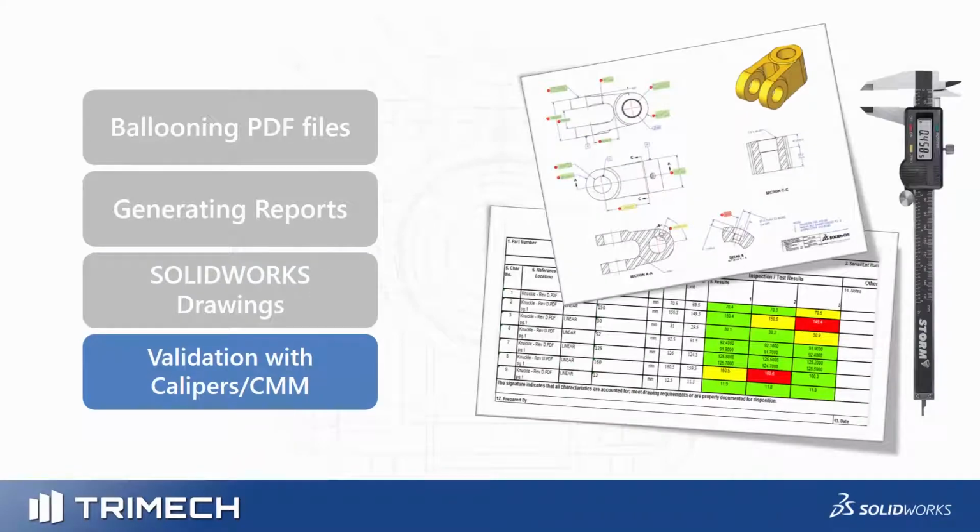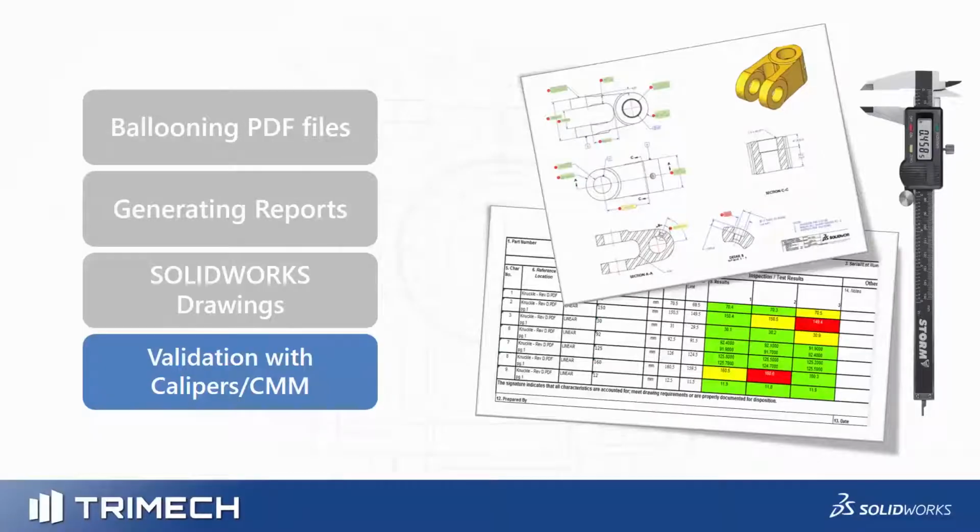So what we're going to take a look at next is validating this information with actual measurements. Now that we've got a report generated, we're going to take some measurements off some real-world parts and enter that information in to check and see if we're good or our parts need to be scrapped. So today we're going to be inspecting with calipers, which have a USB interface directly into my computer.